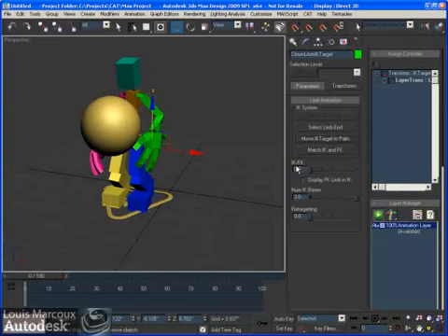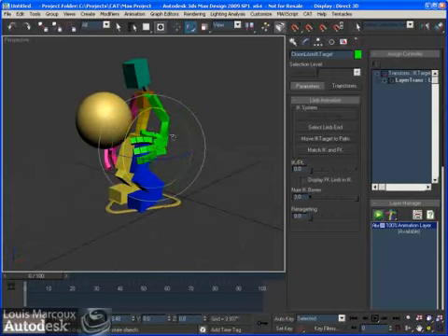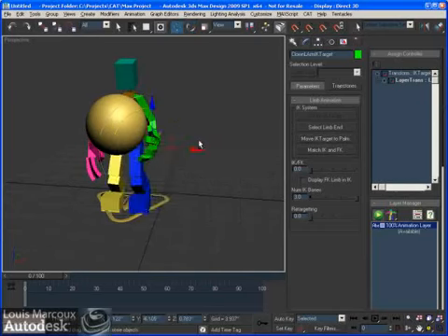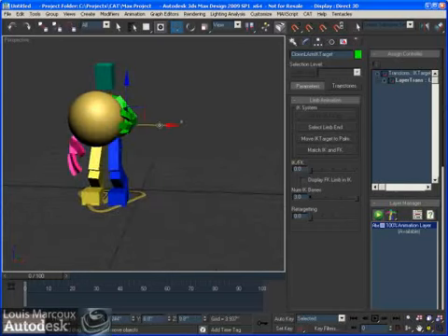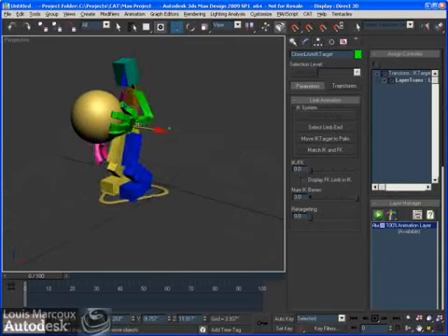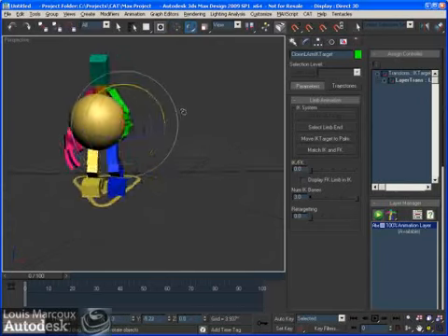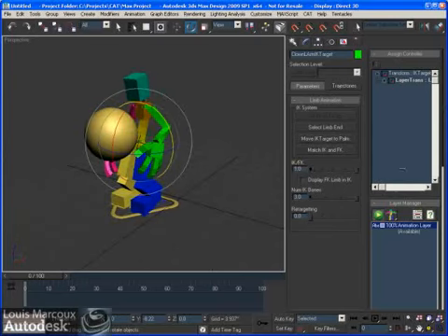So if I try to move the IK and FK solver slider, you see that it just stays exactly in the same position. So it's great for when this is exactly in the same place. You just go into IK, and now I can grab this and rotate the end and place it exactly where I want it to be for holding this balloon, like that. I'll rotate it a bit more. So now I'm just placing the IK target, and if I go back to FK, it goes back to where it was at the beginning. Now it's going to try to reach that balloon like so.